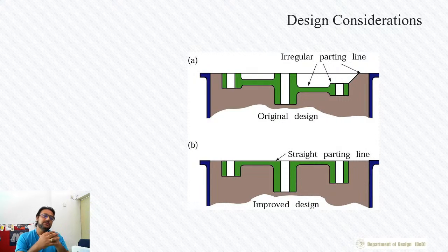So generally you simulate these castings, and when simulating you can clearly see if there are problems of misruns and cold shuts or other issues. I think things like inclusions are not clear, as they depend solely on the properties of the sand and the molten metal. Whatever you can see in the design aspects, you can clearly see the problems that may arise.